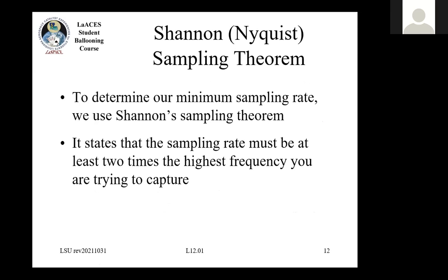And the idea of that is you can see those actual variations. Right, so you want to see it, in one sense, start at its maximum, see it go to its minimum, and then see it return. So that's the idea here, this is the minimum sampling rate you need to actually be able to see that something is happening at that speed. If you want to see more details, you'll increase that somewhat.